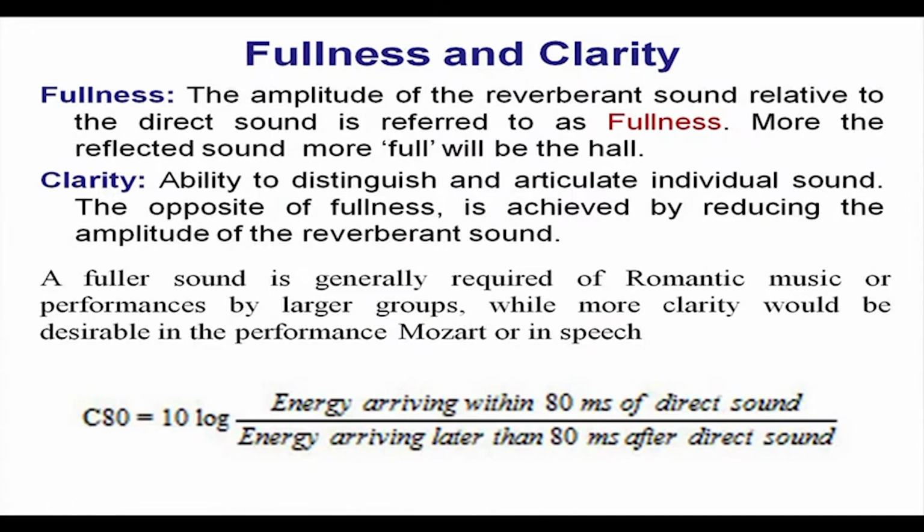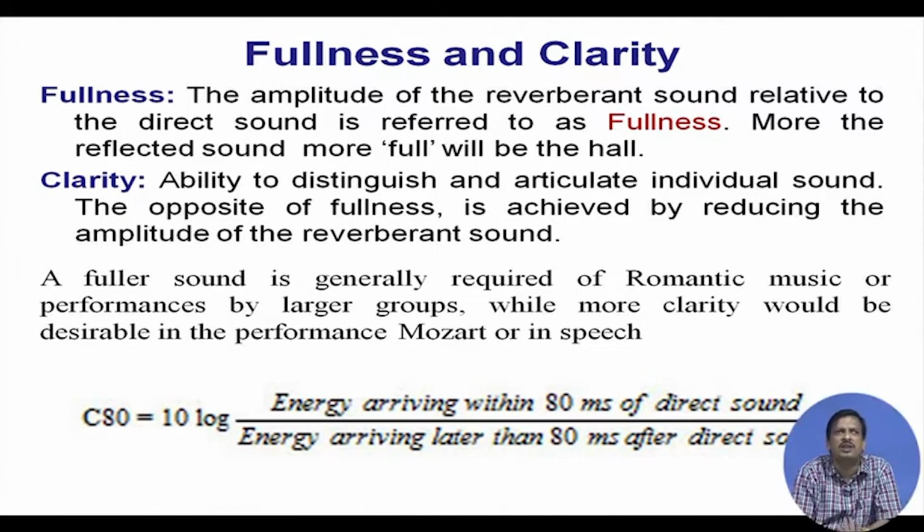Then fullness and clarity. What is fullness? The amplitude of the reverberant sound relative to the direct sound is referred to as the fullness. So, the reverberant sound divided by the direct sound defines the fullness. More reflected sound means more fullness. So, fullness is nothing but the reflected sound intensity divided by the direct sound intensity.